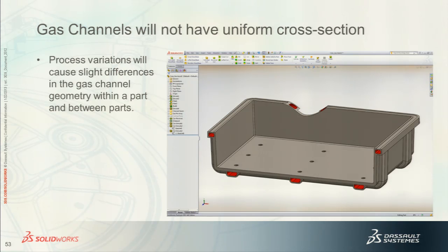I would recommend, if you do look at gas assist for a process, you find somebody who does a lot of gas assist molding, and then take advantage of their experience and expertise and let them help you design the part. So get in touch with a gas assist injection molder early on in your product development.